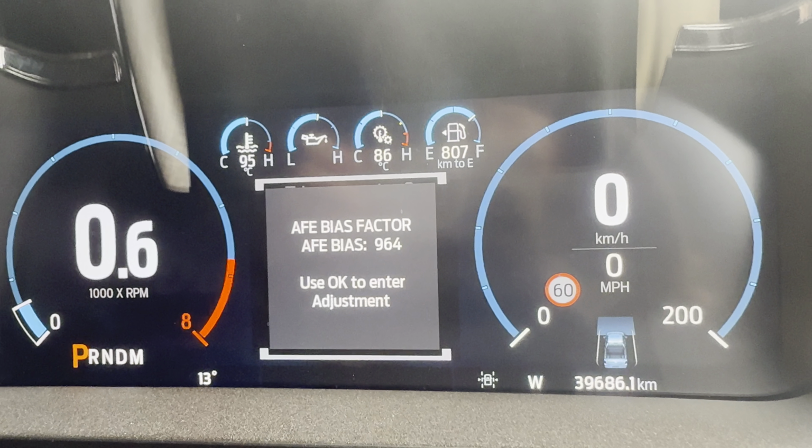If your truck is reporting better than actual fuel economy hand calculated, then you need to lower the number from 1000. If the truck is reporting worse fuel economy than your hand calculated, then you need to raise the number. To bring back the truck from being optimistic, I've had to lower my number.